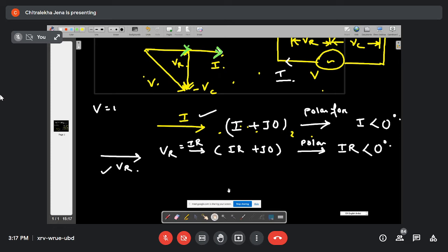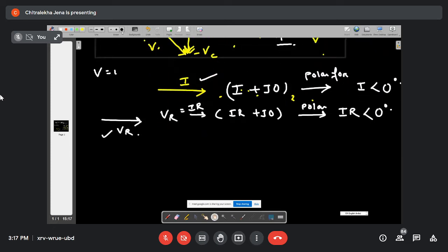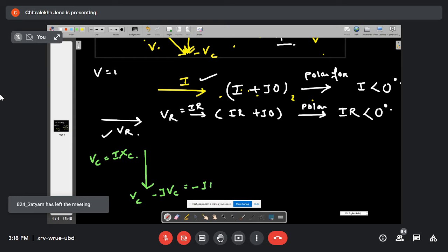Okay. So now come to VC. I am talking about only VC. VC is in the downward direction. So how will I represent it? This one's magnitude is your VC. I will write it as minus J into VC. Yes or no? So this will be minus, and what is your VC? VC is equal to I into XC. Understood or not? Yes. So minus J I into XC. Got it, all of you?